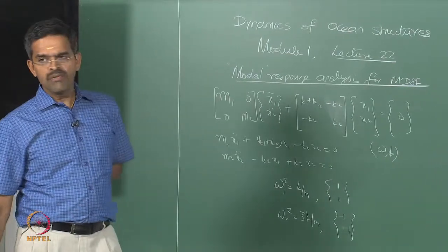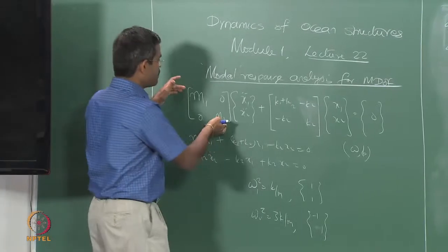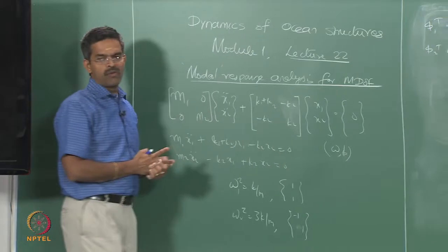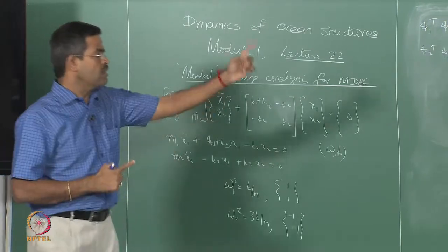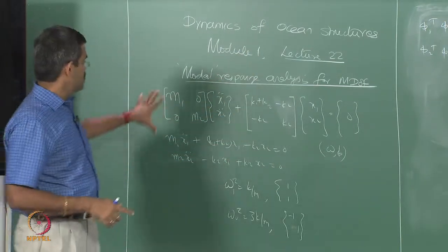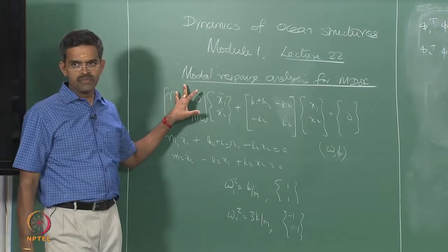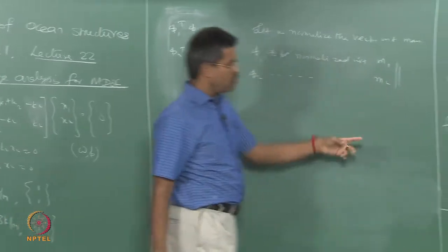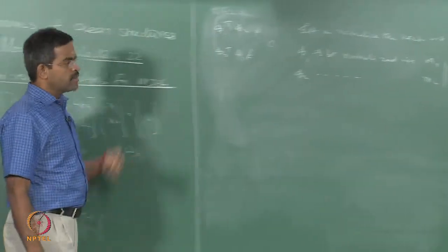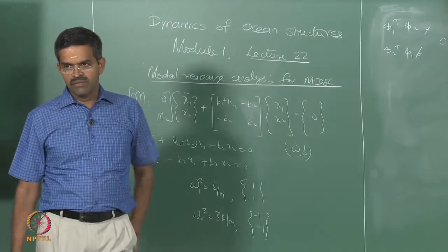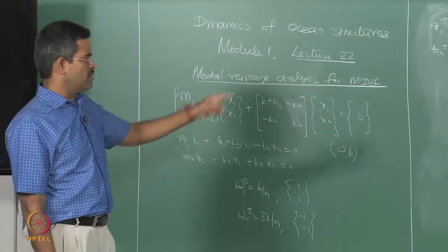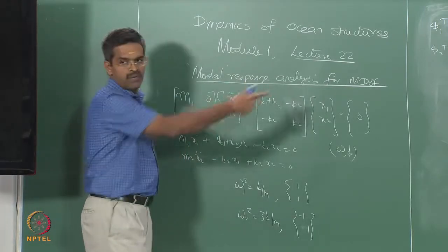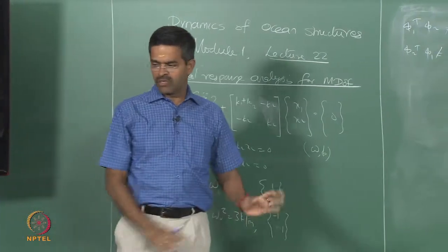So, in a given system, if you are able to identify the mass matrix and lump them in a specific location where you want to measure the displacement, I think 30% of your dynamics problem formation is complete, because all the exercises are focusing only towards the inertia forces. Okay. I could always normalize this with respect to k also, I will show you. If you do it with respect to k, you will get back the eigenvalues actually, I will show you how it is done. Therefore, we do not want that, we want this. Okay. The advantage is off diagonal elements are 0, you get a greater advantage. This will decouple the motions now, equation of motion will decouple, we will see how.